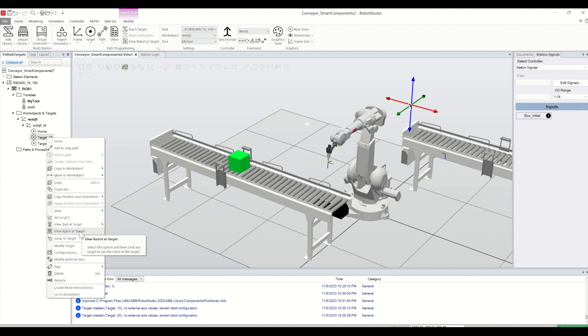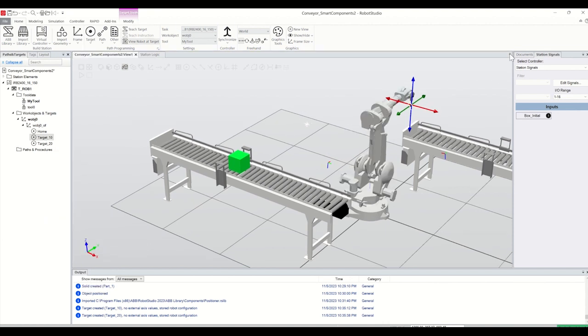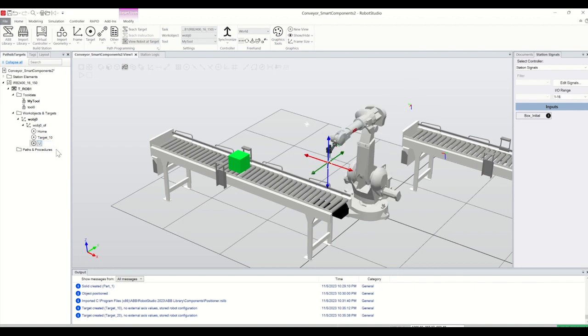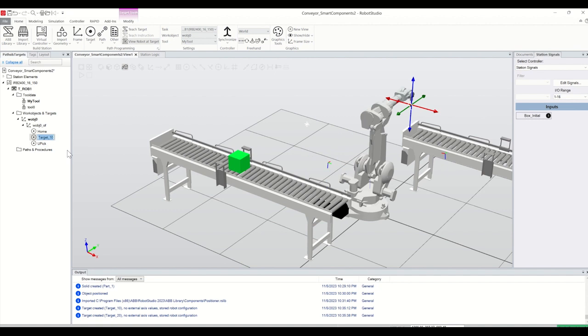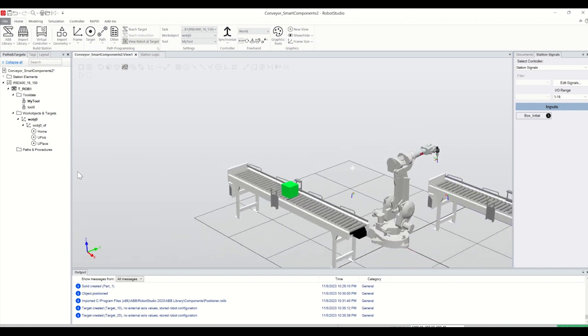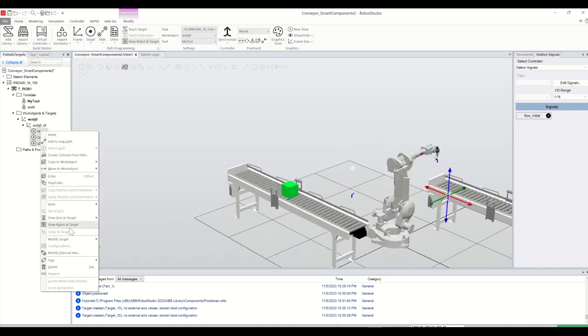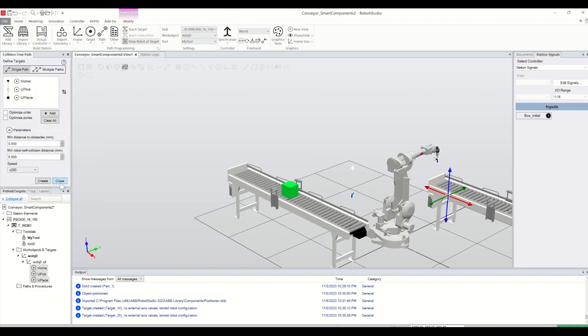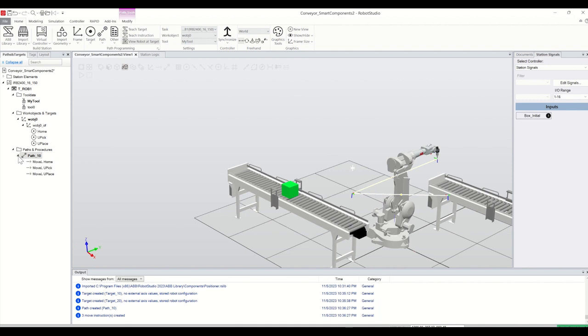And if I want to see the robot at the target, then basically there's the pick, and this one and that one. So maybe I can name this one as U pick, and maybe that one as U place, right? So now I would need to make a couple of options. But before starting the controller related work, I want to see whether the toolpath I made is going to work, right? So that's why I would need to go and add a new one, and the idea is that it will pick, it will go to home, and it will go to the place position, right?